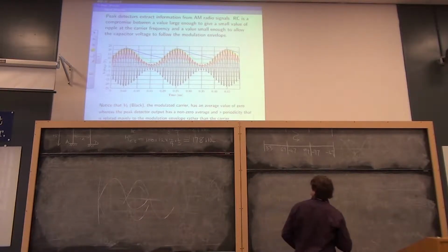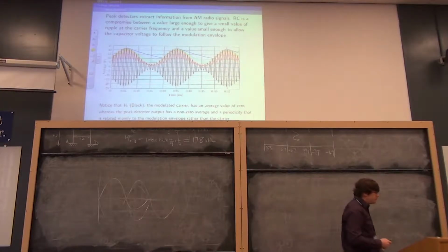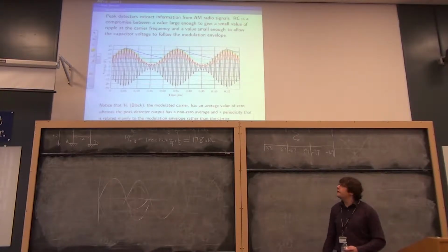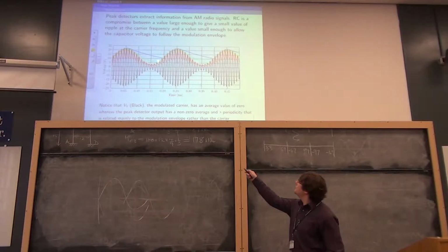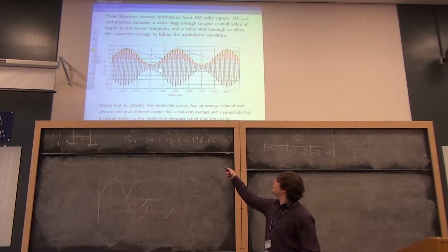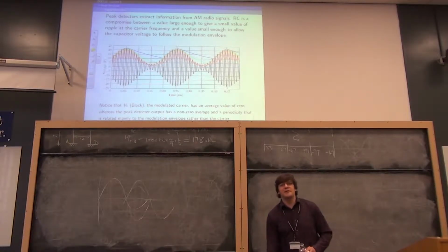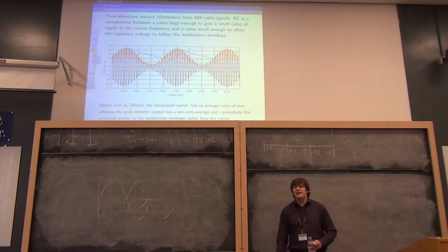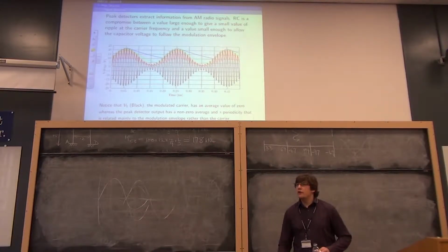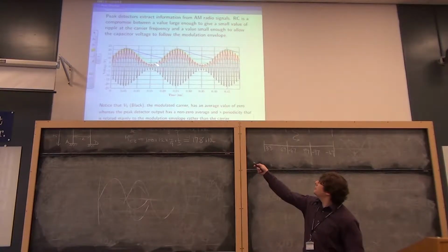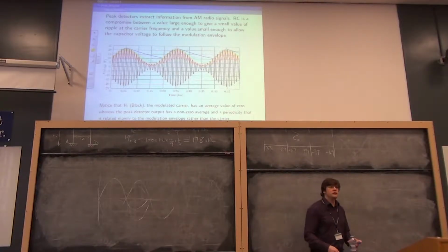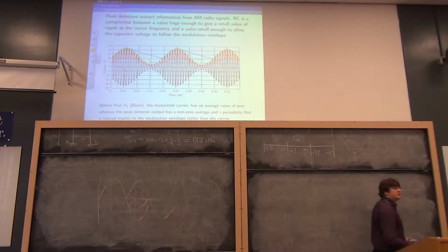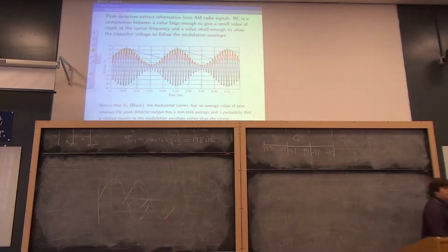Taking the green one, same problem. Not quite as bad. There's still some staircase in here, and there are still misses here, so it's not very good. And the yellow one, you think, oh, the yellow one looks about right. Not really. It still just about misses. What you have to have is a bit of a staircase, even in the lowest point of the modulation. And once you've managed that, you know you're always following the modulated signal. And if you're not following the modulated signal, you can't recover it nearly as well as you ought to.